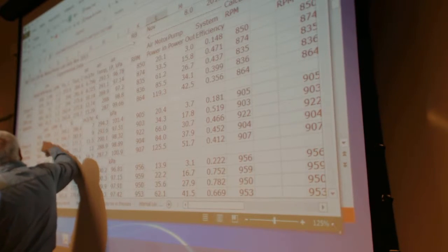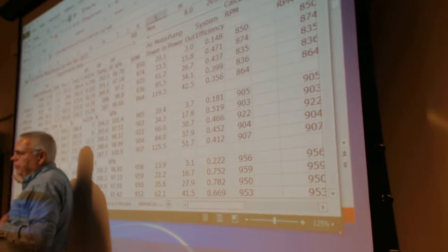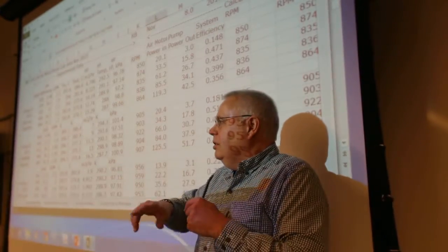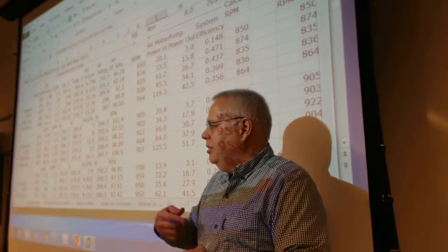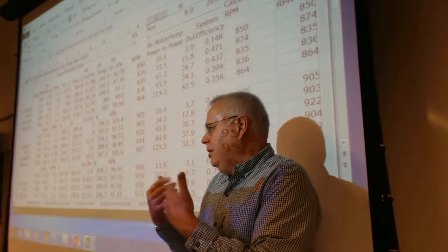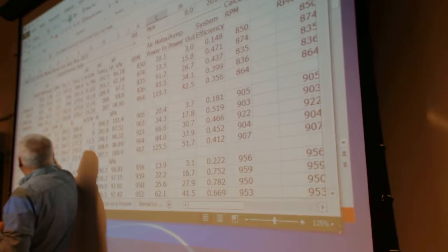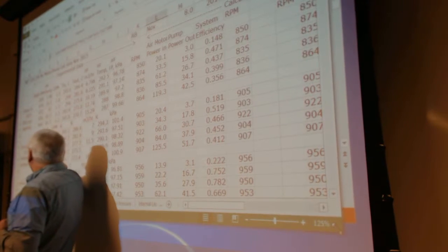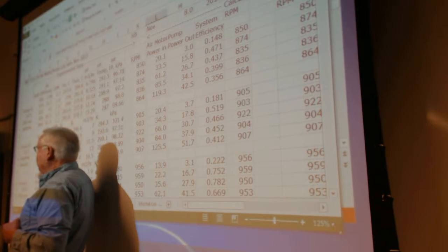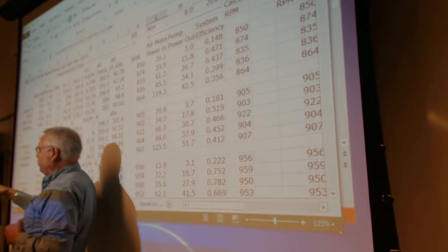The other thing, at a given RPM, and that's why this RPM matters, there's a certain volume of fluid that's pumped forward, and it's always the same volume being pumped forward by the gear teeth. But as the pressure comes up, more leaks past it, right? Higher pressure, you get more leakage. So at essentially 0 pressure, it turned out to be 4 psi, you get the highest volume flow rate. But as the pressure increases, it's still pumping the same amount of fluid forward, but the difference between this and this is how much fluid's going backwards.